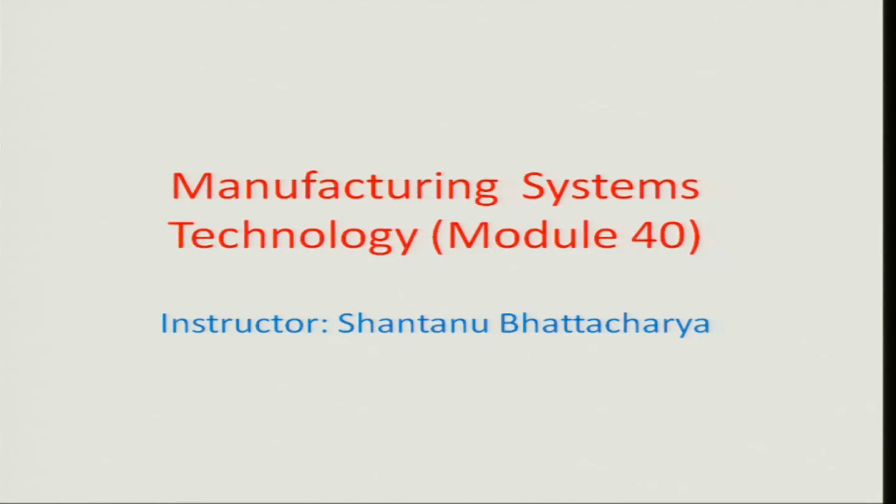Brief recap of what we did in the last lecture. We talked about the various canned cycles, and there are certain G codes or preparatory codes which are available for representing the canned cycles, including the basic operations like drilling, counter boring, and so on. We also illustrated some of the basic G codes needed for linear interpolation and rapid point-to-point positioning, which is otherwise executed using full speed of both the motors of both the axes.